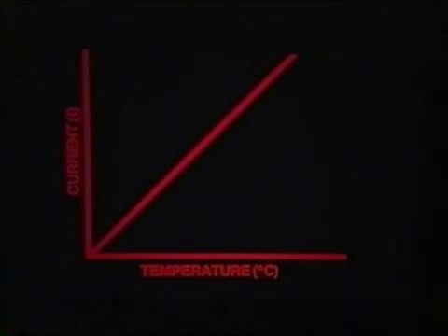When current flows in the windings, this resistance will cause a warm-up of the windings in direct proportion to the amount of current flowing in the winding. Therefore, when a winding is loaded to its maximum rated current carrying capacity, its temperature increases to maximum, and thus its resistance will also be at maximum.